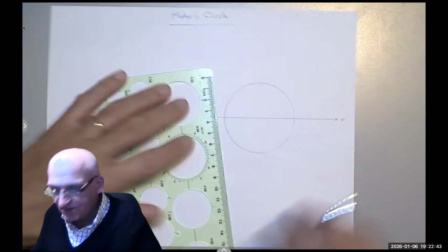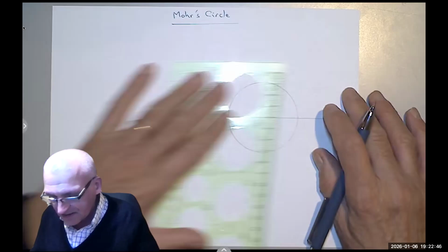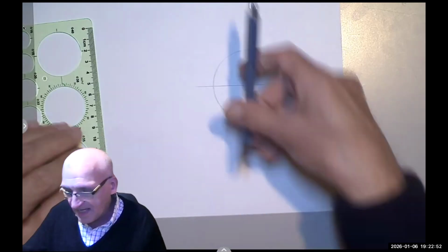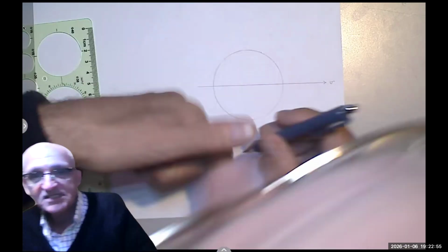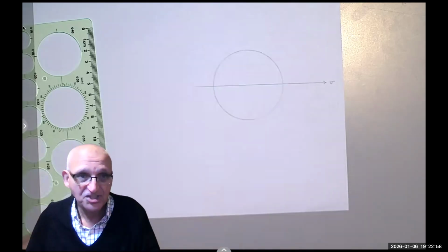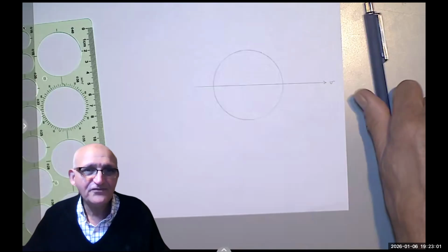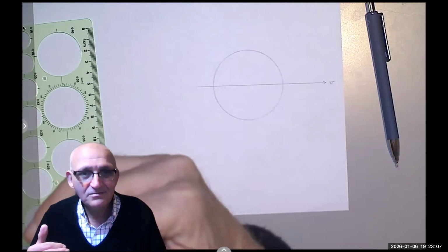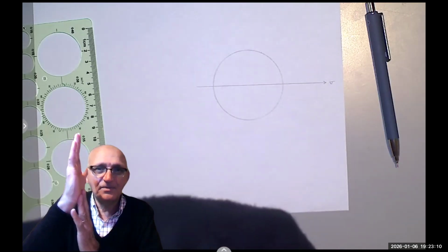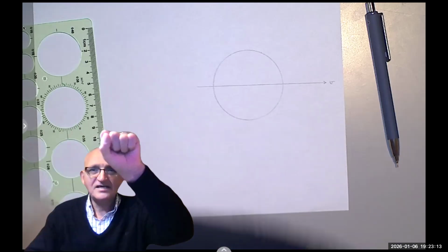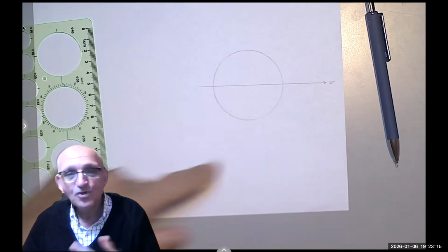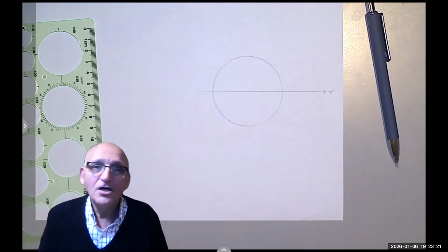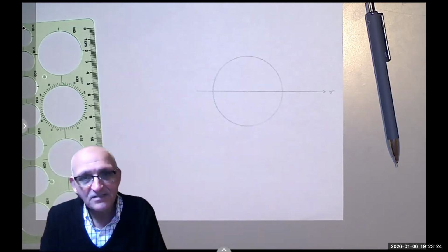And the shear stress would be, so to speak, the y. I don't know the location because the location depends on where the zero is. But I am going to assume, just for simplicity, that bottom is positive and top is negative for the shear. Notice for the shear, there is no difference. The material doesn't feel anything different if you apply a positive shear or a negative shear, right? It's just you are trying to split it into two like that or like that. It's the same thing. However, for the normal, of course, it's either tension or compression. So depending on whether the material is brittle or ductile, it makes a big difference.